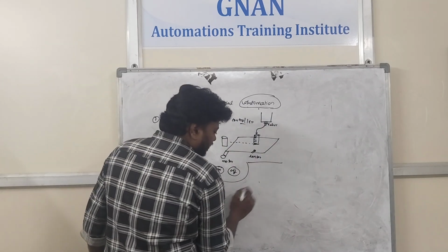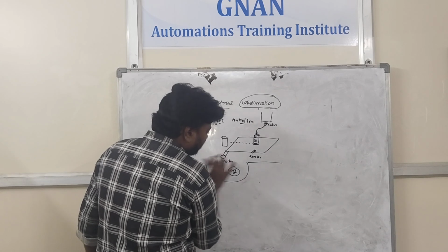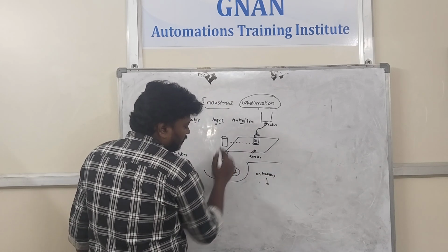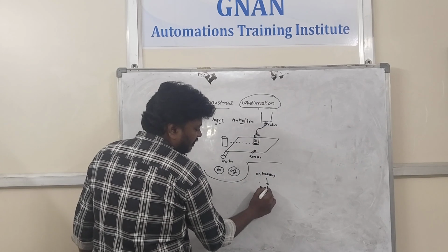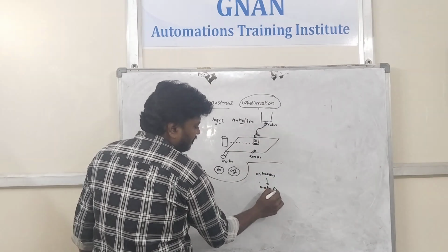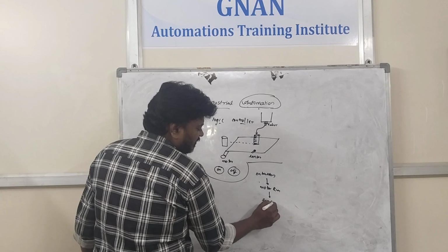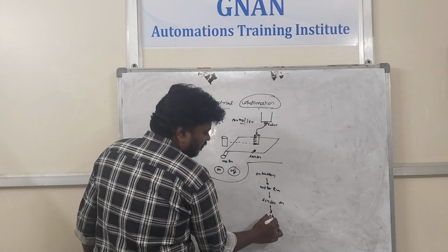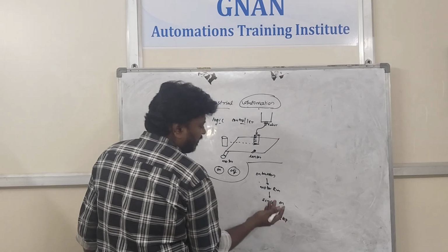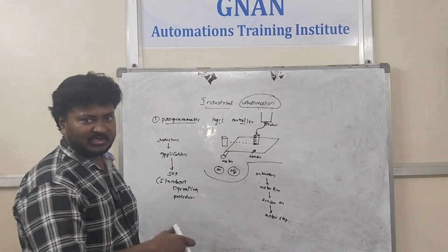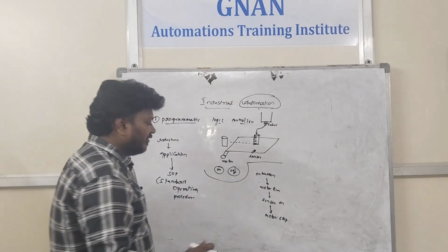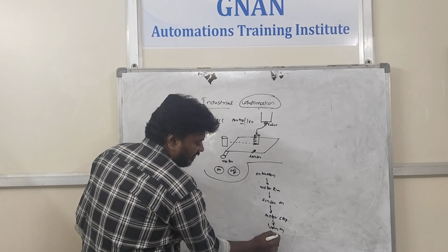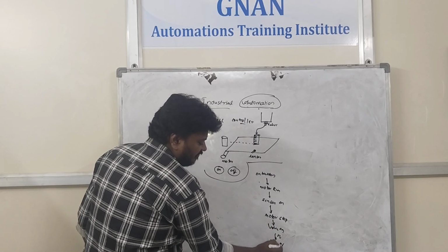We are going to write this in a step-by-step procedure. For example, the first point is we turn on the on button. Through this, the motor is running. The next step is the sensor detecting the object. Sensor on. Next, when the sensor is on, the motor should stop, right? When the conveyor stops, only then can you do any procedure like filling or capping or labeling. Once the motor has stopped, next the valve runs. After 5 seconds, the same valve goes off.